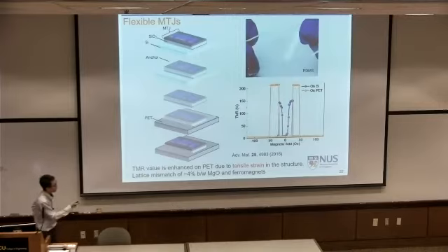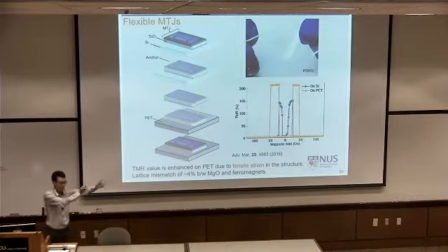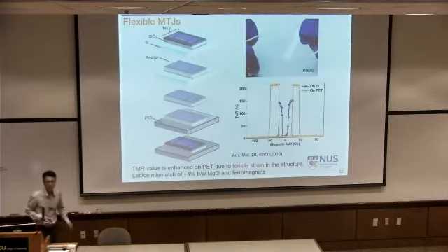This square behavior is known as magnetostriction. So once you have a magnetic domain and you stretch, what happens? Your magnetic domains align better in one direction, then your magnetic response will be more abrupt. So that's what happened, this very abrupt response. But the enhancement of TMR cannot be understood using this conventional magnetostriction theory.